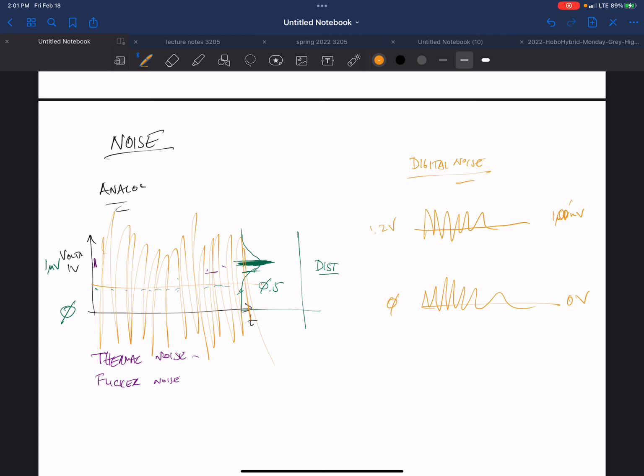very correct. But your worst enemy sort of is yourself when you're a digital chip, because you're the one that's turning on and off, and you're the one that's being confused by other blocks in you turning on and off, right? So it does help that the lower voltage you are, you typically tend to create less noise, but it doesn't make up for the fact that the lower the voltage you have, the more susceptible you are to making a mistake.